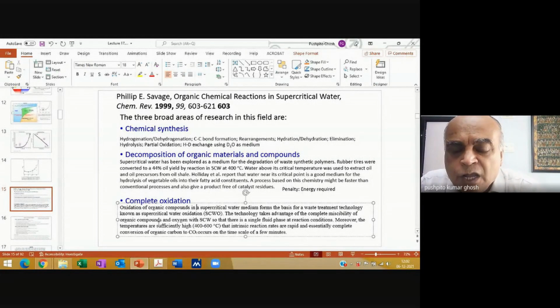And so what happens is that when we do all these biological or chemical oxidations to convert all organics in effluent into carbon dioxide, I need oxygen, right? I can promote a more efficient reaction simply because I've got such a high concentration of oxygen.